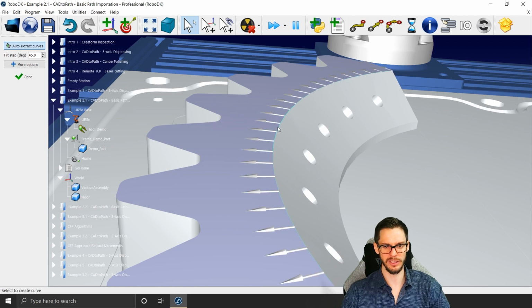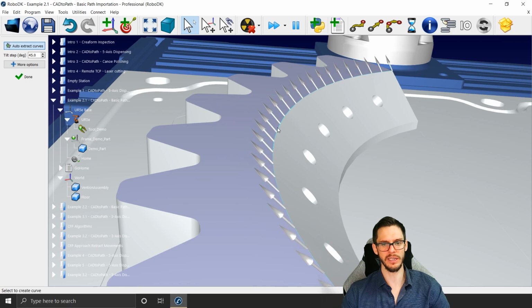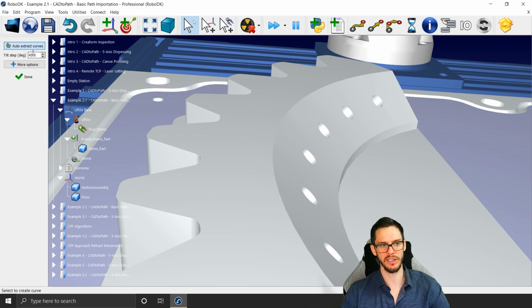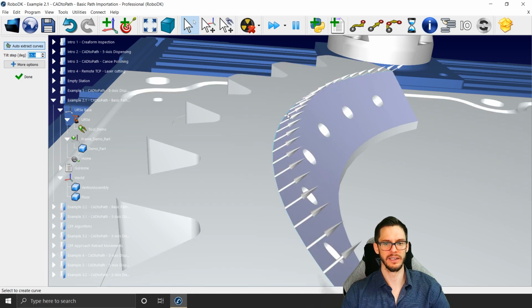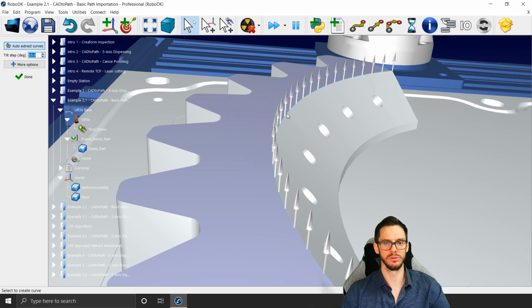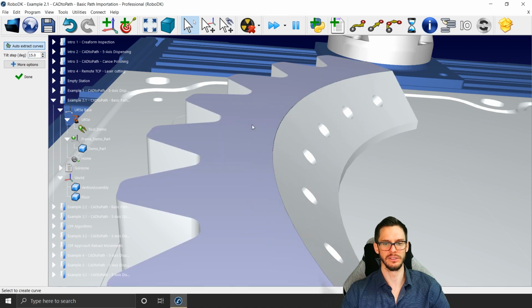Let's say that I come here. You can see that if I move my mouse a bit, I have some different tilt possibilities. This is driven by the tilt step. If I go for 15 instead of 45 and come here, I have different options. Starting from here, 3 options to reach 45, 3 options to reach 45 the other way around here, and 3 options to reach 45 here also.